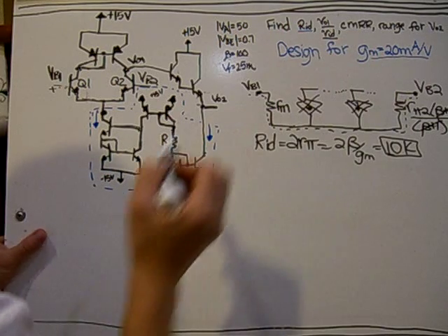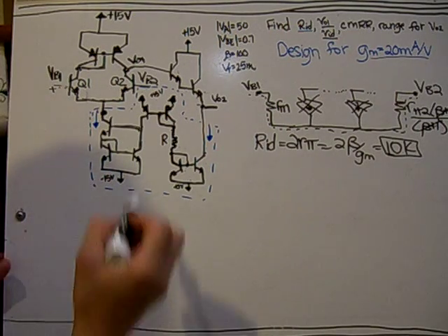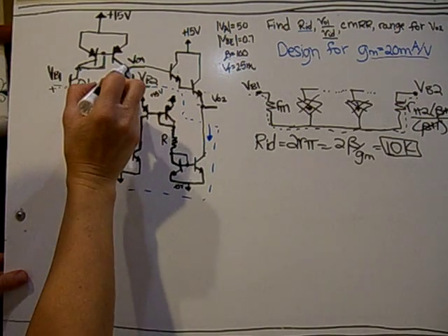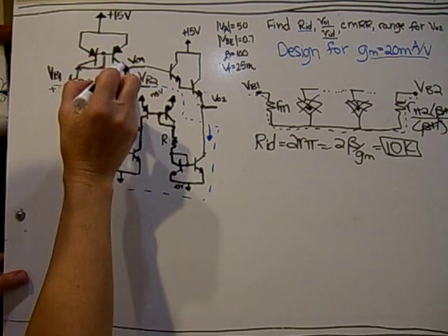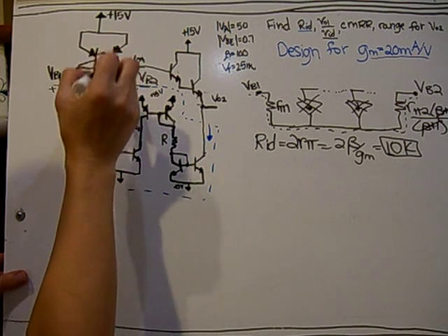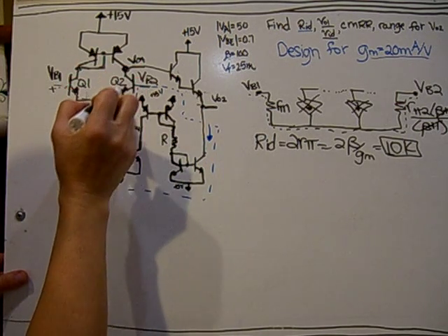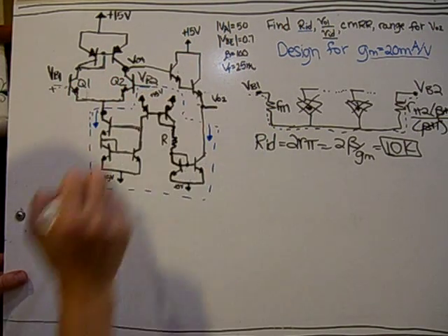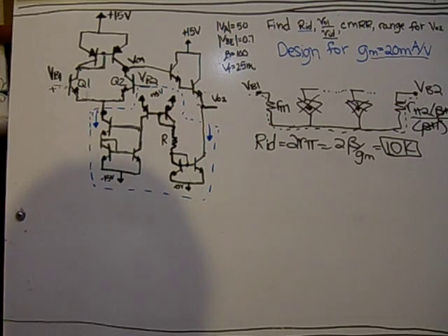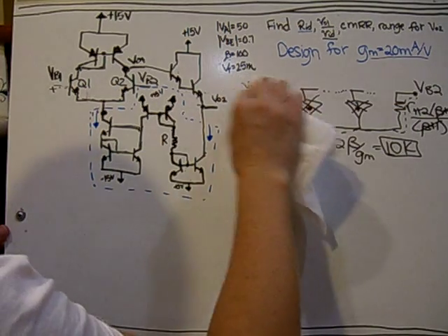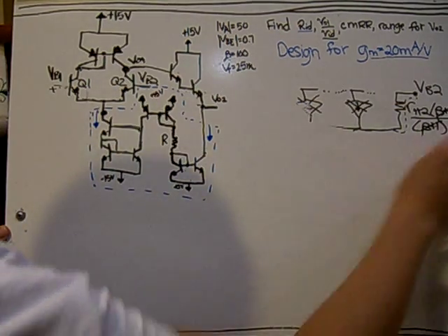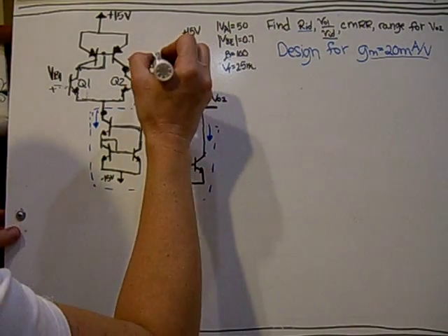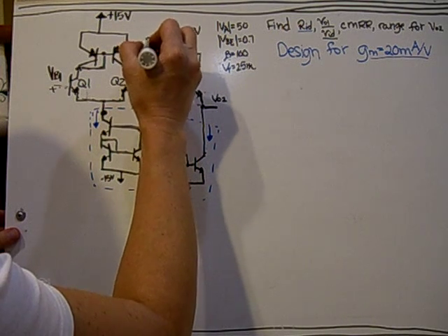The next step is to find the gain VO1 over VID. VO1, which is located here, has this, which is RO2, or RO, whatever the RO resistance is of that one. This one, which is RO2, and then whatever's seen over here for the Darlington. So drawing the Darlington portion to find the equivalent resistance at VO1. So we want to find an R equivalent here.